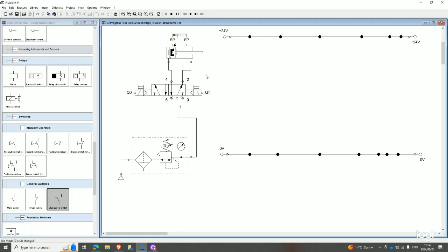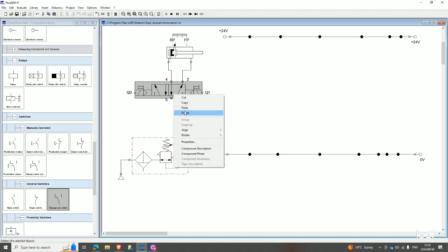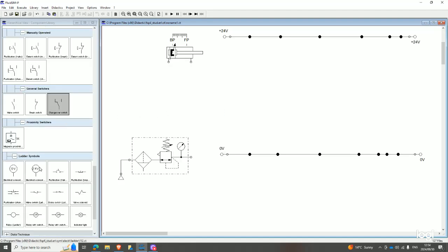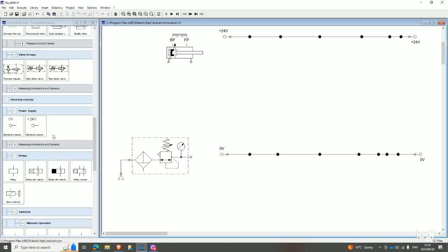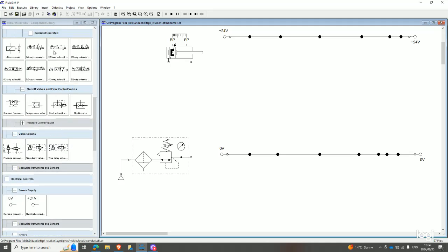If we're trying to latch using a dominant braking signal, we can't have a bistable 5-way, which already has a latching mechanism built in, and then come back to build a circuit that has a latching mechanism as well. So now we'll use the spring-loaded one, which doesn't latch, and then we'll latch that signal to make it stay in that position. So we want to latch the signal of a spring-loaded 5-way.